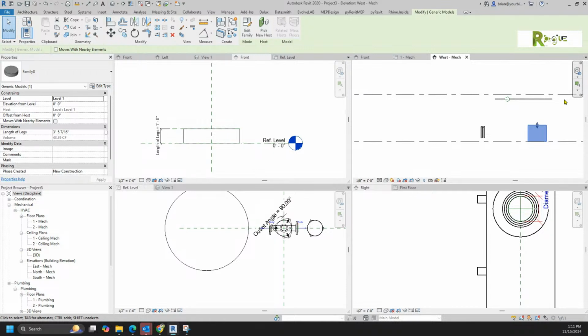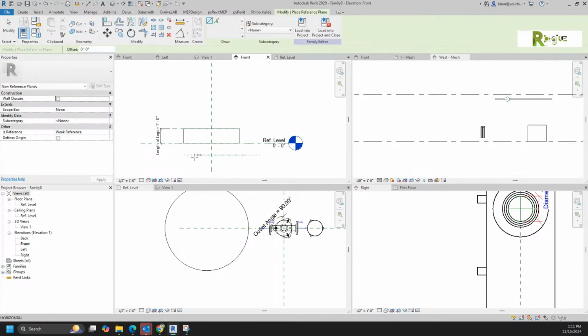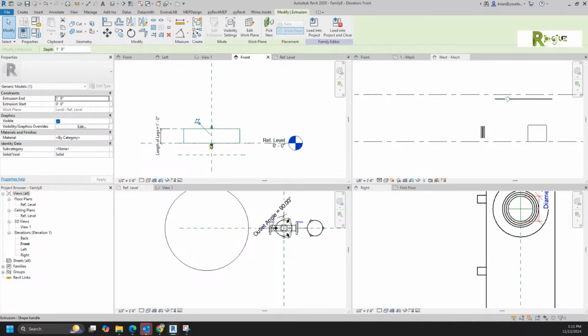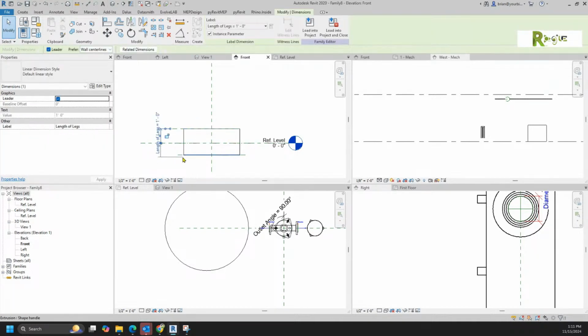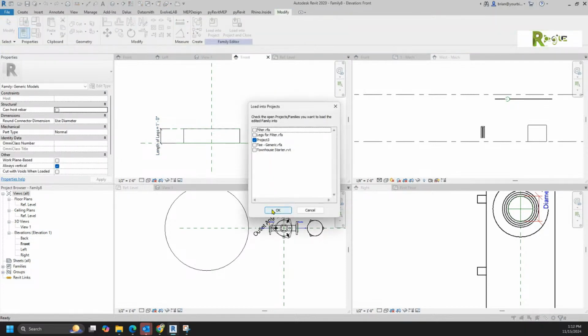Well, it's because you're tying it down at the bottom. You're only having the dimension go up, right? That must be. So to answer your question, if I created another reference plane and said this was the bottom, and I took the length of legs, now it'll work all day long. That's what it needed to have happen. Well, watch the difference. Project 3.